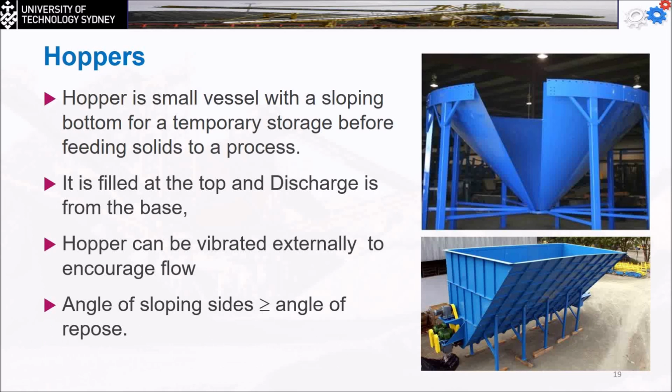The angle of the slope is usually going to be more than the angle of repose of the material we're going to have. That is theoretically, but actually in the design process, we're not going to use the angle of repose directly. There's something they call the rule of thumb. You have to know the angle of repose of your material. Then you choose the angle of the slope of this side to be higher than the angle of repose. That's, once again, the rule of thumb.